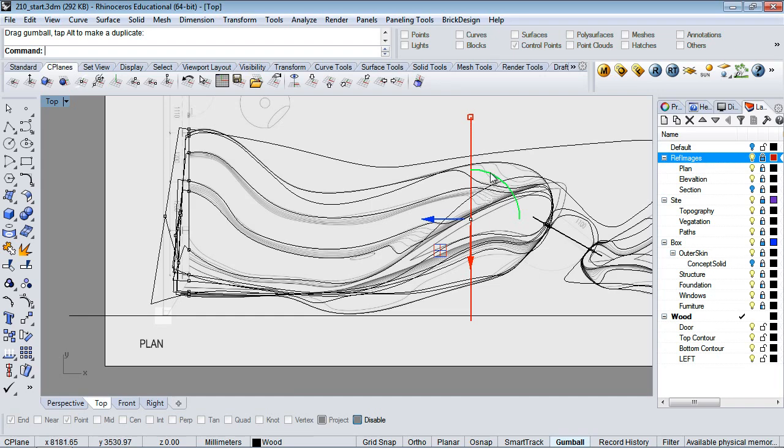But if we're looking at this point here, and that becomes a real critical point, then I might want to rotate this tool to be perpendicular to that. But use that on a case-by-case basis. So for right now, what I'm going to do is rotate it this way because I really want to focus in on this transition area between the two of them, where we go from 3 steps down to 2 steps. And so I'm going to want to control that transition a little bit.